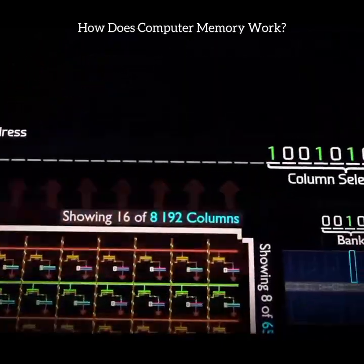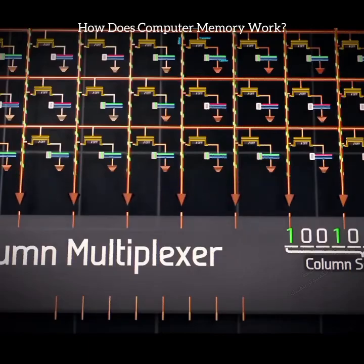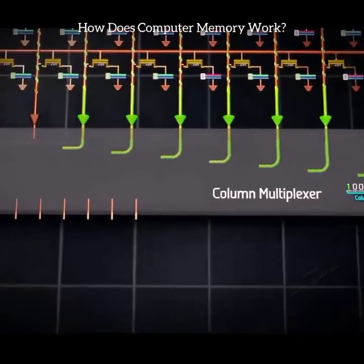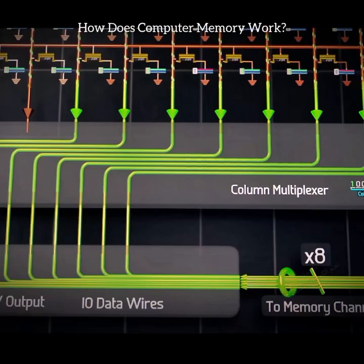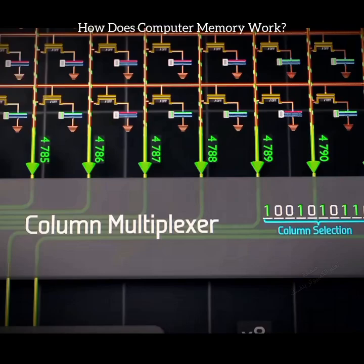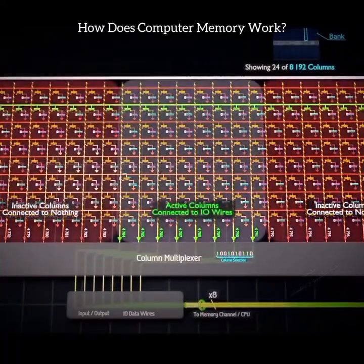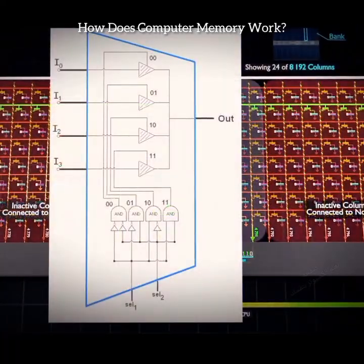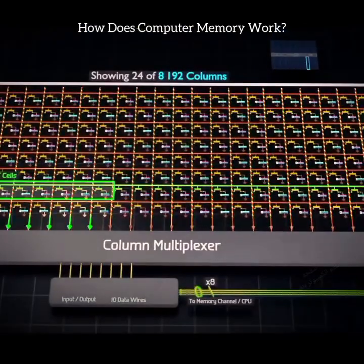The remaining 10 bits of the address are sent to the column multiplexer. This multiplexer takes in the 8,192 bit lines on the top, and, depending on the 10-bit address, connects a specific group of 8 bit lines to the 8 input and output I/O wires at the bottom. For example, if the 10-bit address were this, then only the bit lines 4,784 through 4,791 would be connected to the I/O wires, and the rest of the 8,000-ish bit lines would be connected to nothing. Here's the logic diagram for a simple multiplexer. We now have the means of accessing any memory cell in this massive array.